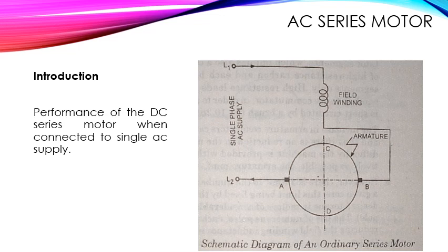The field winding of a shunt motor is wound with many turns of fine wire so as to limit the field current but give high flux. These many turns of wire cause a significant inductive effect, resulting in a high reactance and so a high impedance. The result is a very low field current, much lower than that required to develop sufficient starting torque.